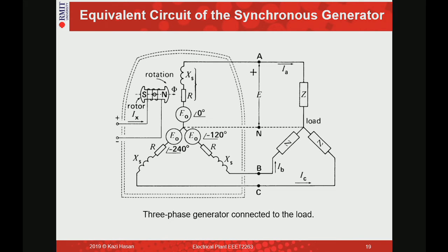And what we see here is a three-phase system. All of the voltage magnitudes are the same. If you connect that to a balanced three-phase load, this is Y connected. For simplicity in our discussion, we can convert this type of circuit into a per phase equivalent, so we will just consider one phase.